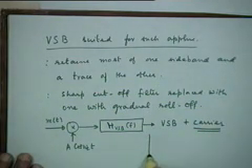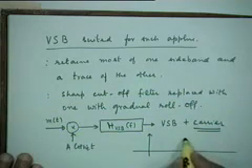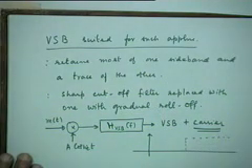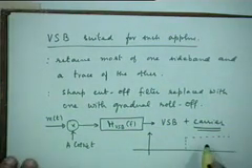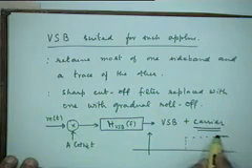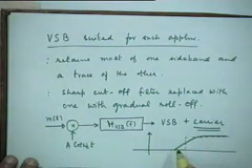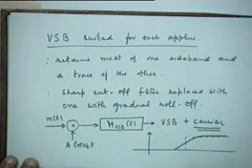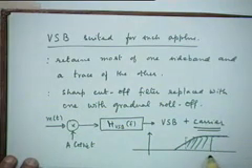And this H_VSB(f), suppose we want the upper sideband, it will not now be a filter which has this ideal requirement, right? It will indeed allow a gradual roll off like that. So you will be transmitting most of the upper sideband. Let's say the bandwidth is B, right?